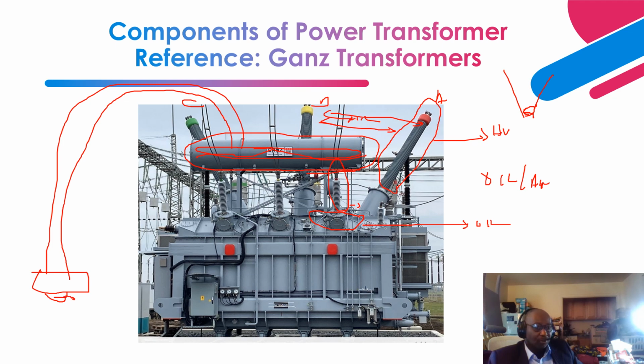And you have holes that allow air to flow through. So the breathing in of air goes through those holes, and the oil layer regulates the amount of air that is taken in. So this is your silica gel beads.